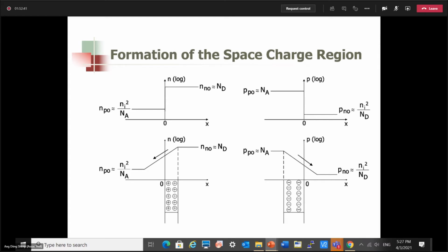Is the drawing of the negative and positive donor and acceptor just below the axis just a way of representation? Oh yes, that's right. I just want to show that due to the diffusion of the electrons in this diagram, for example, the positive donor ions will get exposed. So this region here, where the electrons have diffused across, will become positively charged. So it's a schematic representation.